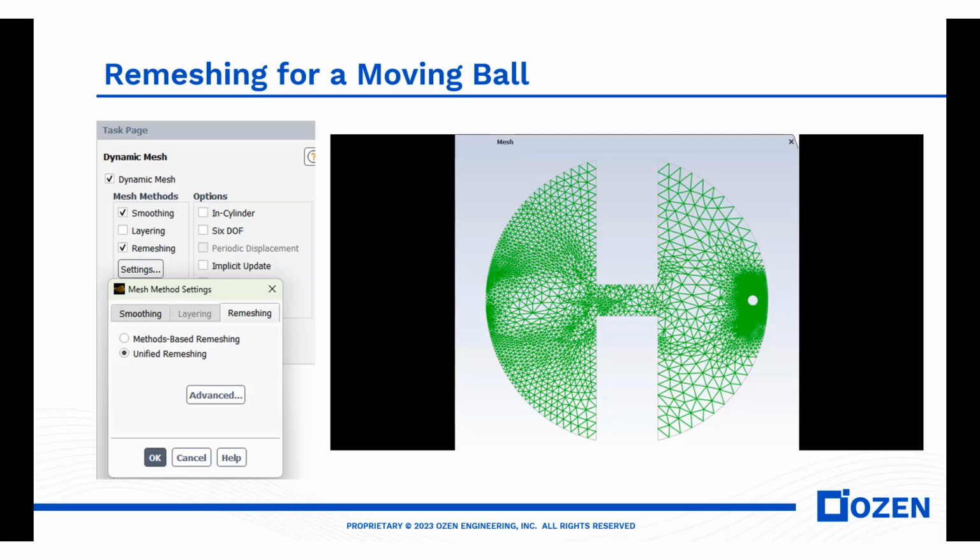Don't forget to always preview the mesh before really running the simulation, and you also need to find a good and appropriate size for the time step, and then compare that with the time step for the simulation. The smallest will be the one that should be used when you start running the Fluent model with dynamic mesh motion.